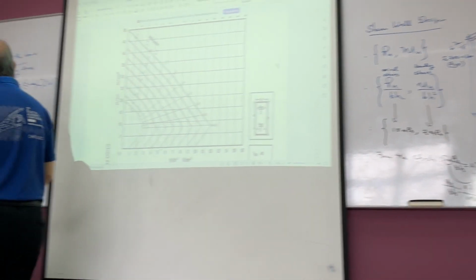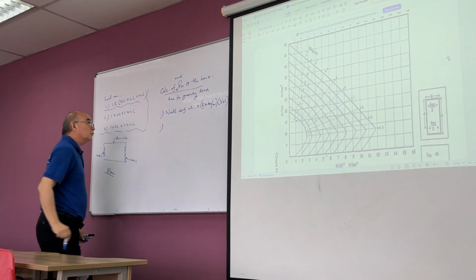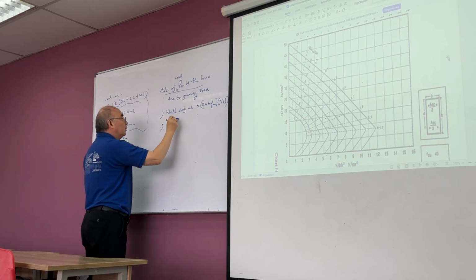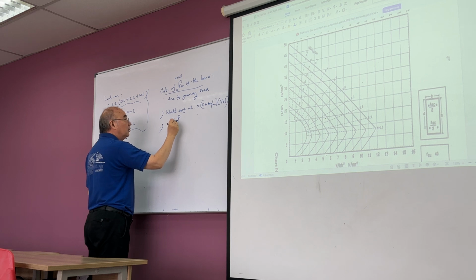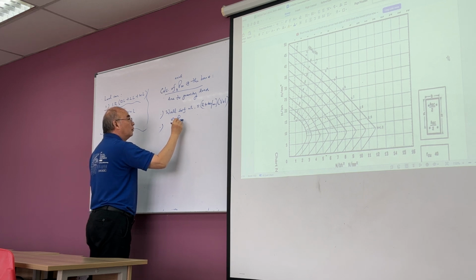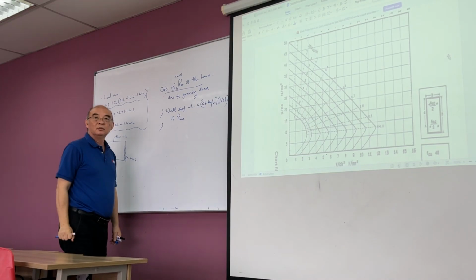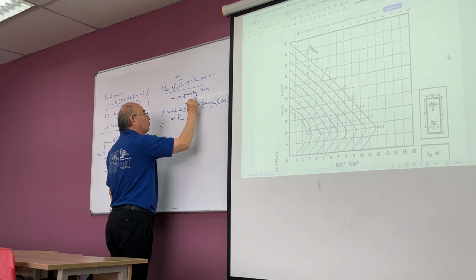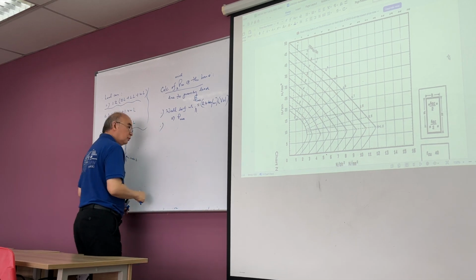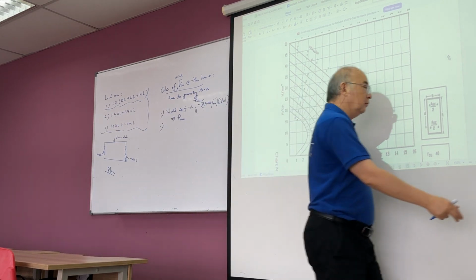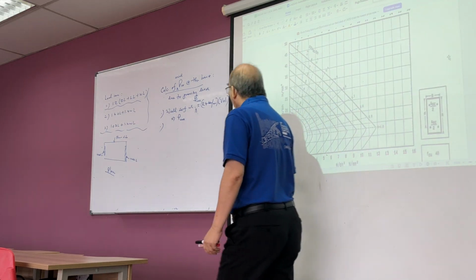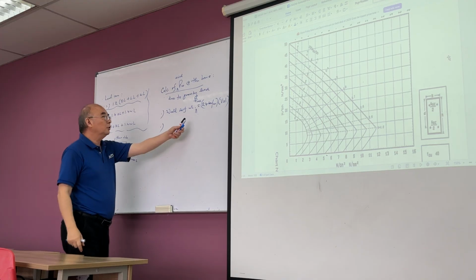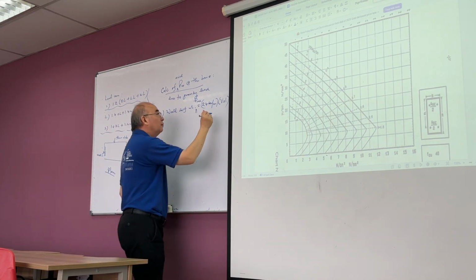Now, okay. So this one will give you the P of wall. Understand? This self-weight of wall, P of wall. So here is a P of wall, right? It's equal to 24 kilonewtons multiplied by the volume of wall.